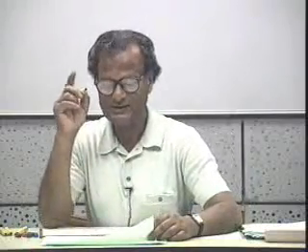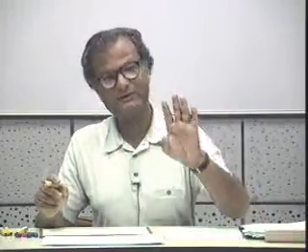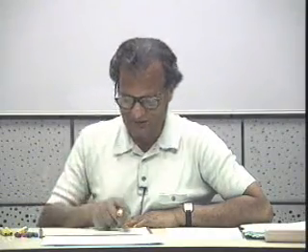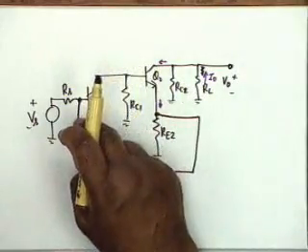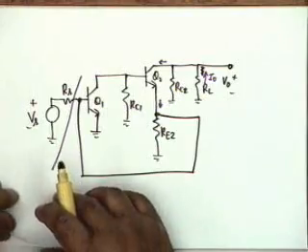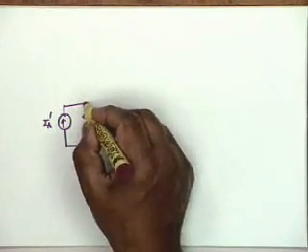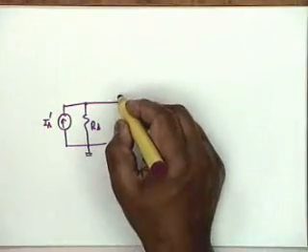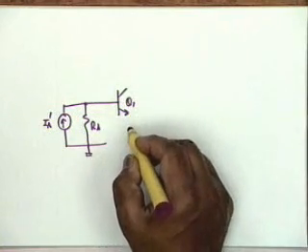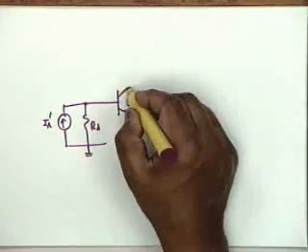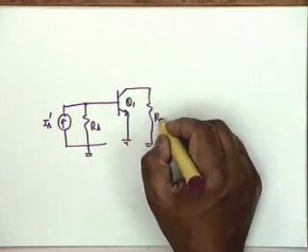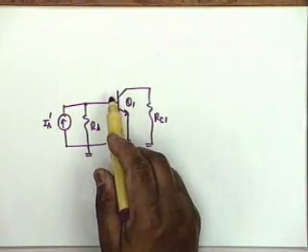Now let us see if we can draw the A circuit and the beta circuit. If it is a shunt-series, what is the appropriate transfer function here? Before you apply those formulas, you must determine what kind of transfer. Current to current or voltage to current? Current to current, because there is a shunt here, and therefore the first thing you should do is convert this into its Norton equivalent. And so I have Is prime, Rs, then you have the Q1, ground, RC1. What will come here from the feedback network?